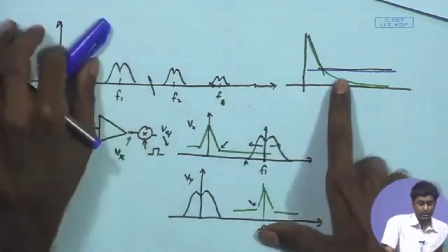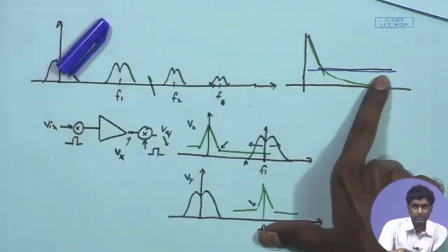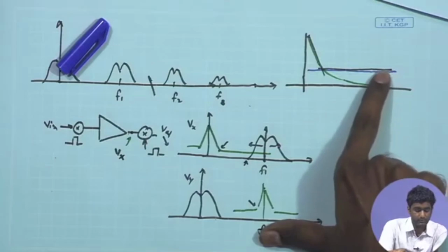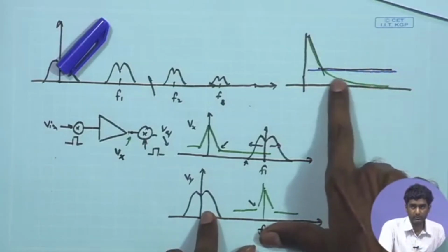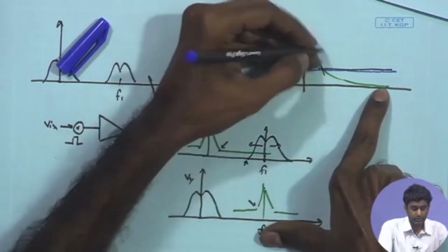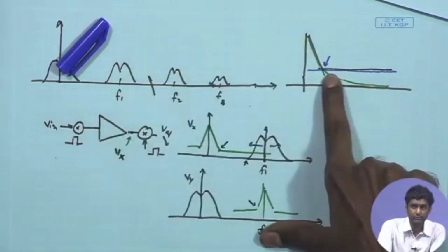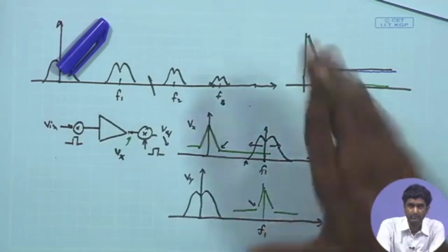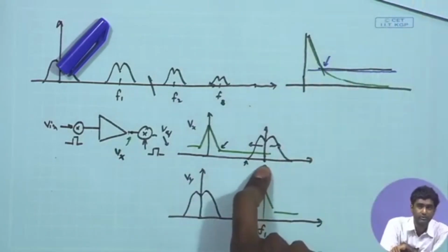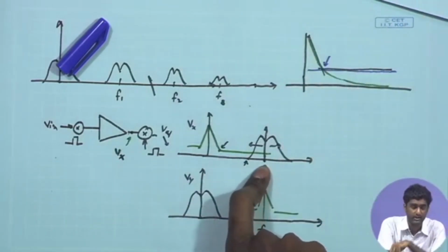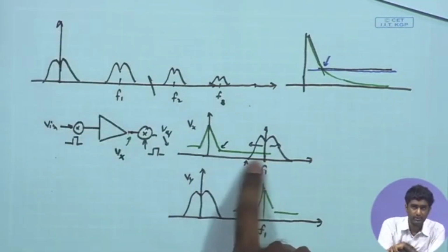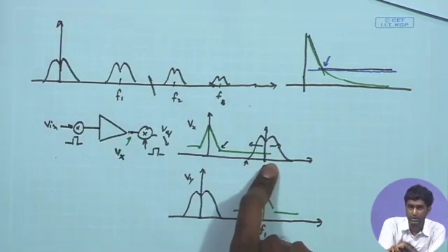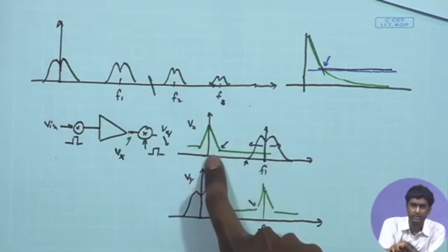So, if we go higher and higher for the chopping frequency, definitely the effect of this 1/f noise will be diminished more strongly. Crudely we can say that the 1/f noise corner frequency is the deciding point. If we make sure that the f1 to which we are shifting the spectrum is sufficiently higher as compared to the 1/f corner, it seems like we can get a sufficiently good input referred noise, and we are able to mitigate this 1/f noise.